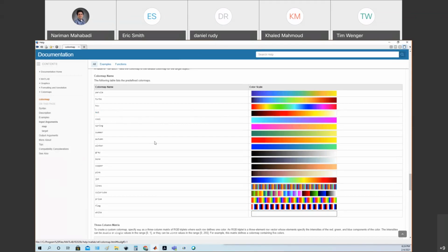For fluid flow problems or even for concentration, we can use this jet option. So jet means the maximum unknown function value would be from blue, and then back to the green, yellow, and to the red. So you have really a wide variety of the options, up to you, but let me just use this jet option.